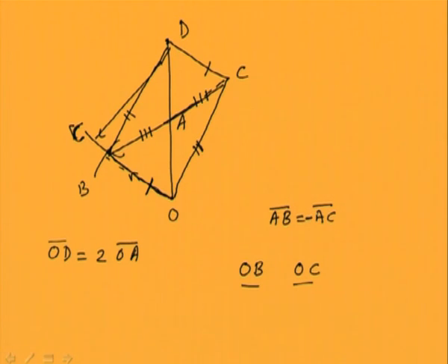Okay, so you can see that now AB is the theta 0 direction, because AB corresponds to the trial mass when we kept it at the 0 location. And the magnitude of the unbalance will be OA, because AB we know corresponds to the trial mass.